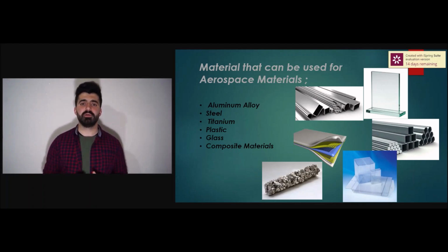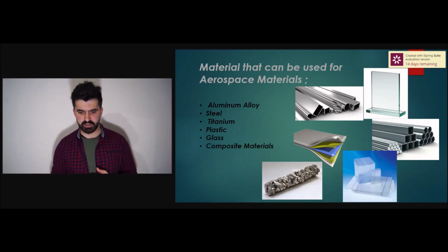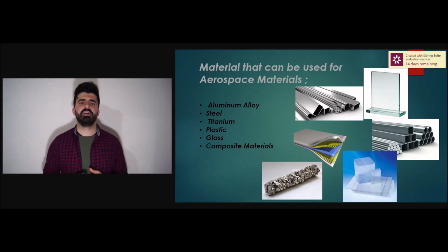Titanium alloy possesses high specific properties, and has good fatigue strength and tensile strength ratio with a distinct fatigue limit, and some retain considerable strength at temperatures up to 400 to 500 Celsius. In general, there is also good resistance to corrosion and corrosion fatigue, although properties are adversely affected by exposure to temperature and stress in a salt environment.